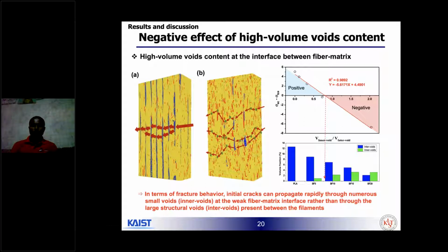So overall, this result suggests that 3D printed composites have relatively many more voids than the mold process sample, but can compensate through the strength of fiber orientation, resulting in a much lighter but stronger material than conventional mold process composite.